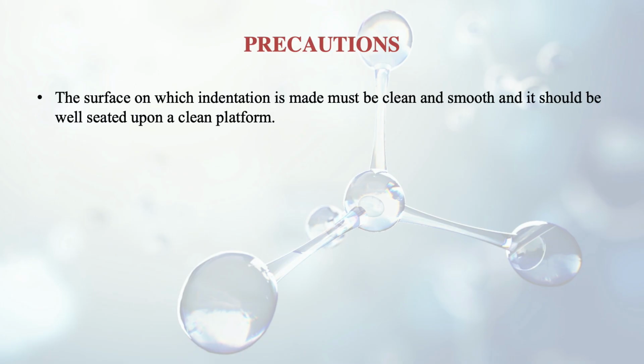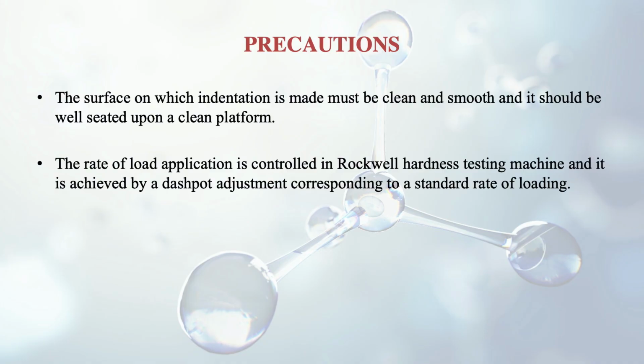Fourth point is that the surface on which indentation is made must be clean and smooth. So cleanliness and smoothness of the surface should be there, and it should be well seated upon a clean platform. The last point here: the rate of load application is controlled in the Rockwell hardness testing machine, and it is achieved by a dashpot adjustment corresponding to a standard rate of loading.